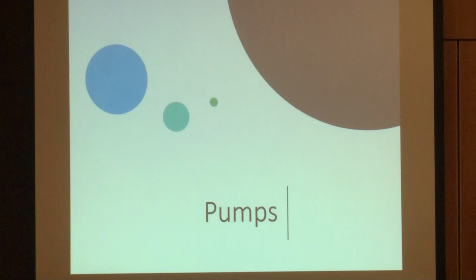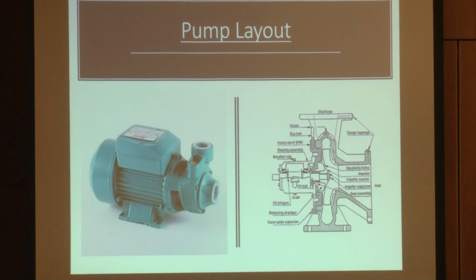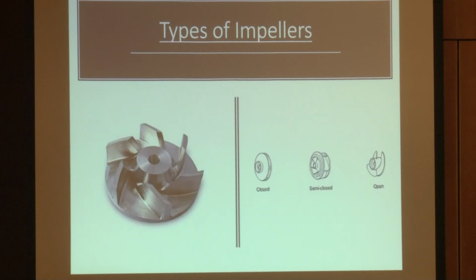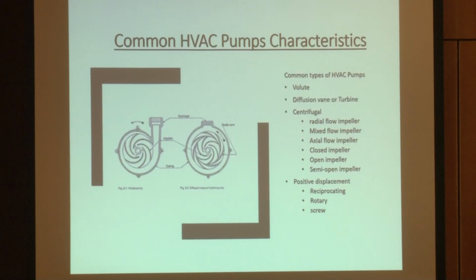Water side, just like the air side uses fans to move the air, we use pumps to move the water. There's a lot of different kinds of pumps. These are just some examples of the pump and the internal layouts of the pump, the kind of impellers that we use to push the water. Obviously, this is the impeller that pushes the water. It can come in a closed, semi-closed, or an open fashion. Depends on your application. The engineer of record will work a lot with the pump manufacturers and the pump vendors in order to figure out what the best one is for their particular desire, right?